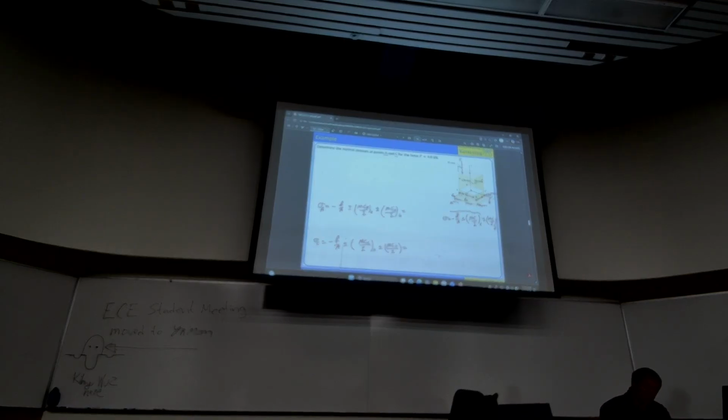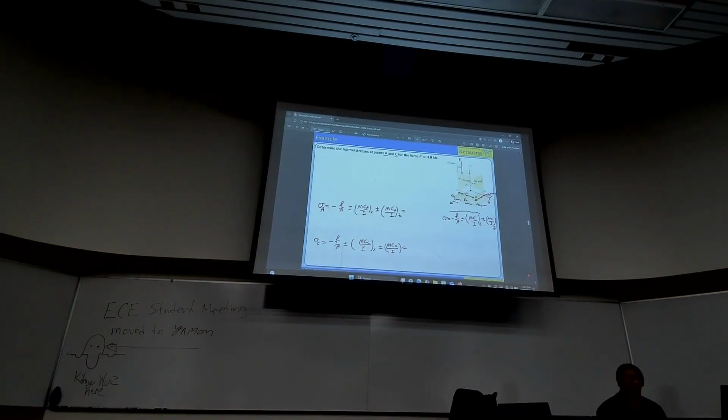Visualize this, F about Z. Does it buckle about Z? Does it curl around Z? Yeah. Oh, okay. So it buckles around 2 axes. Yes. We always ask ourselves that question and then we find the answer to that. All right, so with that said, then we have to calculate Mx, Mz, Ix, and Iz. For the previous example, we did only 1 for each because we had only 1 buckling, but we have 2 now.